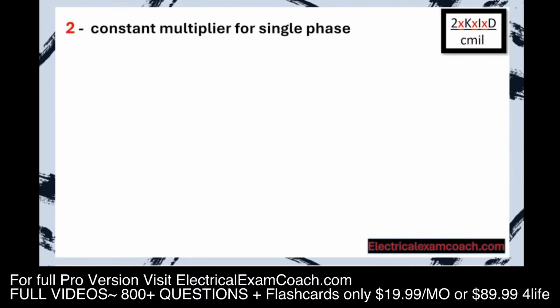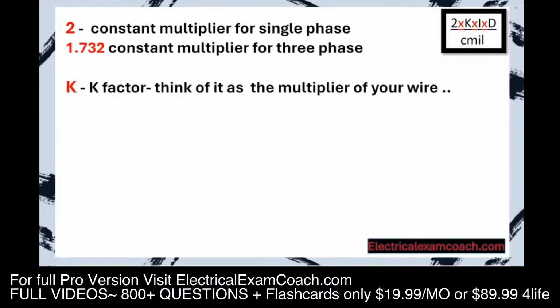2 is going to be our constant multiplier for single phase. If we're doing 3-phase, we're going to use 1.732 as our multiplier. K is going to be the K factor, and I want you to think of it like a multiplier for your wire. For copper, it's 12.9, and for aluminum, it's 21.2. Don't worry about remembering all this. If you're able to bring in your code book into your test, it has it in there. Your state might allow you to write inside your book. You can just write it in there.